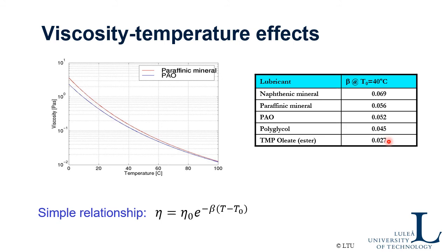That means that the viscosity doesn't fall too much or too fast, and that's good for the heating. The smaller this number is, the less inlet shear heating. Please note that this temperature viscosity relationship is not perfect, but it's good enough for a certain temperature interval.